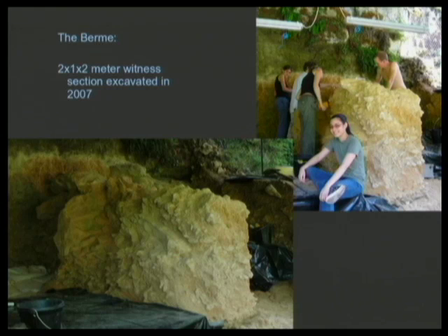And I've been doing this using topographic interpolation. So this is how topo maps are often made, with discrete points that are interpolated into a surface. The math doesn't care if you're dealing with something on the scale of continents or something on the scale of four square meters. So I've actually been quite successful in getting, very quickly, nice three-dimensional digital elevation models for each stratigraphic unit, and then being able to project those into 3D and go back and double check what our excavators thought. And I'm going to walk through this process a little bit using the excavation of this witness